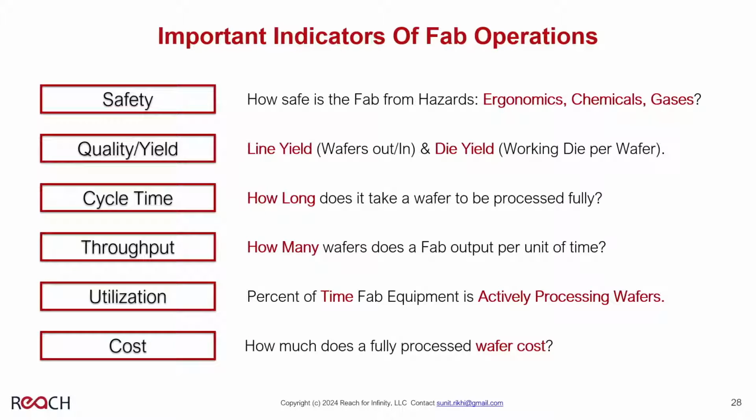And then, of course, die yield. Die yield is how many working die or chips you got on the wafer. There are many, many failure modes, and it's outside the scope of this talk. You can have a defect, a particle land somewhere and create a short or an open. You can have processing control issues, a misprocessing. You can have variation.